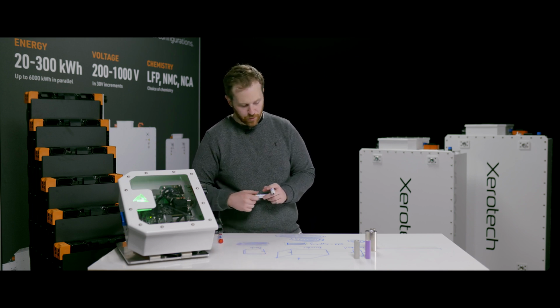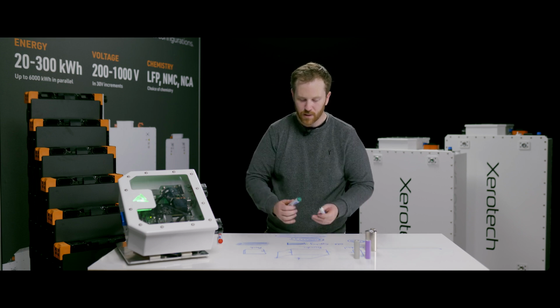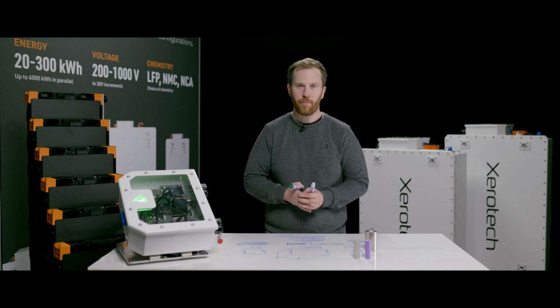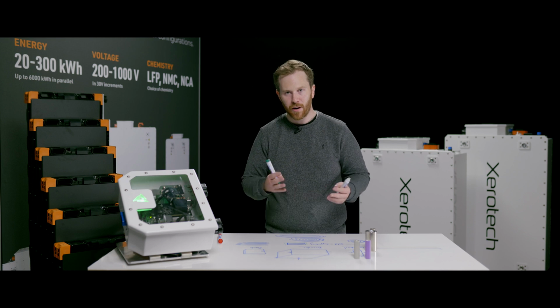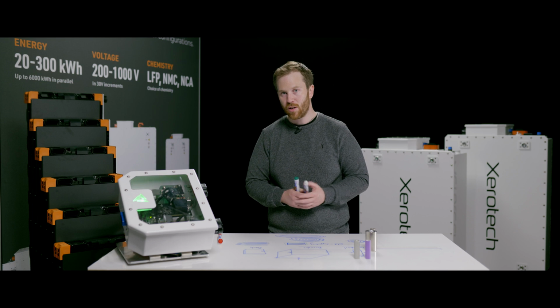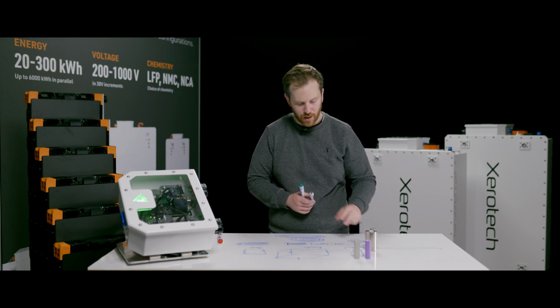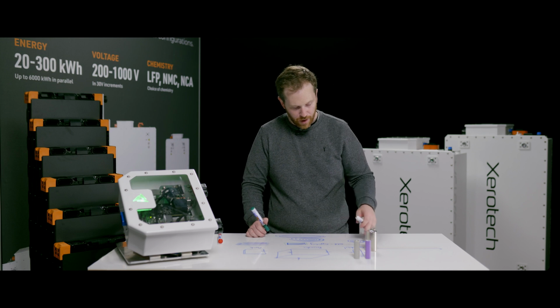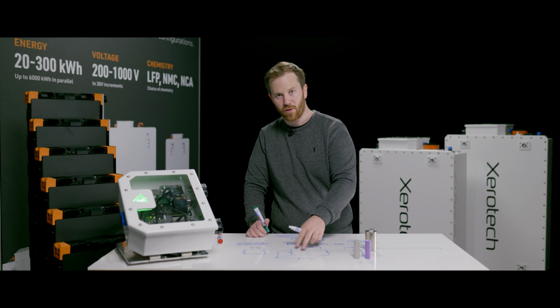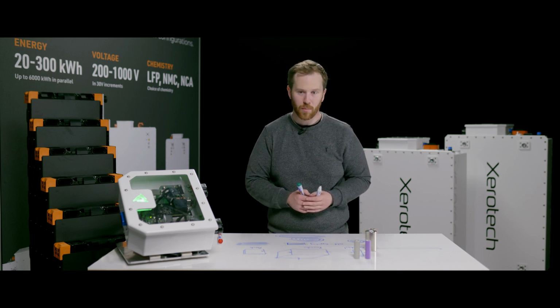There's pros and cons to doing each different type of battery cell. So prismatic cells, because they're bigger, will have better energy density and better volumetric energy density. Pouch cells will also have good energy density, both volumetric and gravimetric. And then cylindrical cells will end up with a very robust structure, slightly lower energy, volumetric and gravimetric, but they have other advantages that we'll come to in a moment.